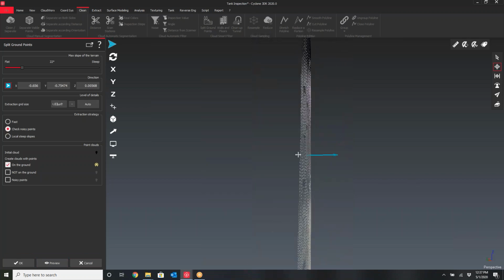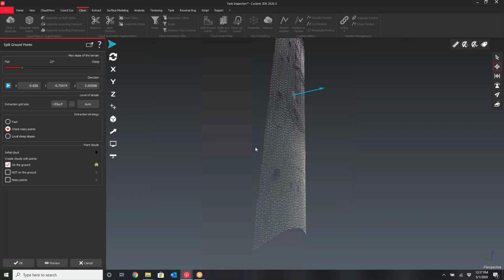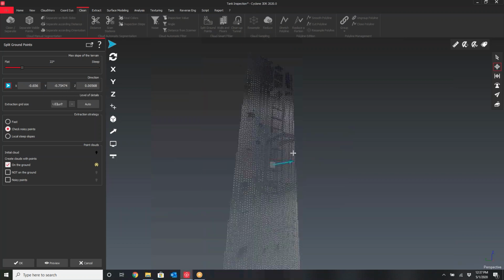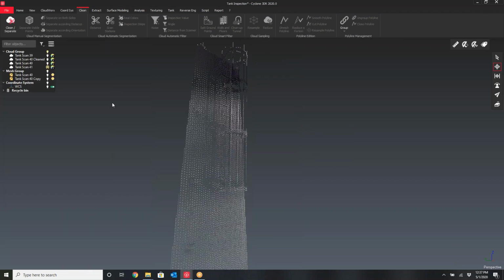All right. So now you can see, just by cleaning off the face of the building, we have a very clean point cloud. It was that easy to just click here, and then click onto the face you want to send your Z out. You can also put in the numbers if you know what they are, like I know that -1 in the Y would have stuck that out. This used the system to pick it. If you want to accept that, we press OK. I've already done so, so I'll just hit cancel.